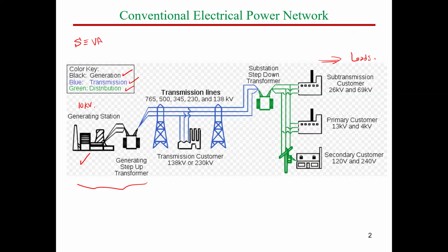So let's say 10 kilovolt and, for instance, 4 kiloampere. If you multiply these two values, it would be 40 megavolt ampere. So we have here 40 megavolt ampere, for instance. If you start transmitting this 40 megavolt ampere without using a transformer, you may end up with this 40 megavolt ampere being dissipated during transmission and not reaching our customers. So in order to avoid that, guys, we start firstly using a transformer.